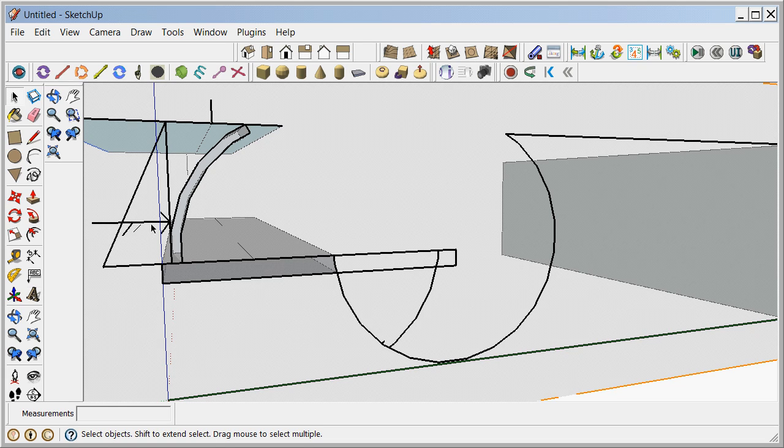At the same time, the resultant of the three forces, this force here, which was the kind of resultant of the triangular pressure, this force here if you had any kind of effective overburden from water above, and then the force due to the weight acting on this kind of semicircular triangle here. If you add up those three forces tip to tail, they will have a direction, right?